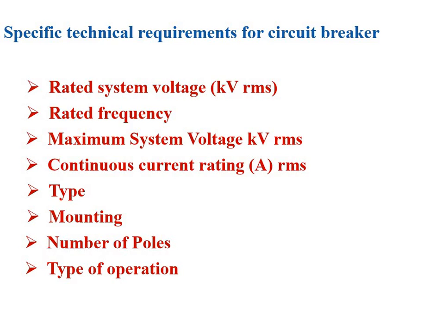But if you require separate operation or individual operation of each pole, then in that case you have to go for 4 single pole circuit breakers for a 3-phase 4-wire system, the individually operated single pole circuit breaker.